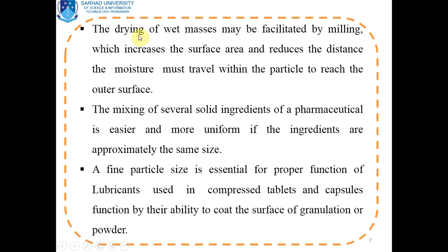Another application is the drying of wet masses. If we want to dry the wet mass or the material that is having moisture content, the wet mass drying will be facilitated by particle size reduction. If we reduce the particle size of the wet mass and then we dry, the particle size reduction will facilitate the drying process.